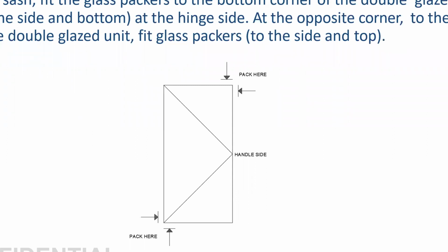The thickness of the packer may be from 2 mm to 10 mm, depending upon the gap between the glass and your outer frame, and the position depends upon how much lifting you need, the profile you have used, and the glass you have used. It depends more on practical experience, on what is practically required. Rather than going theoretically by the charts, one should know the logic of where to fix, and you should carry the packer and some silicone so that the packer doesn't come out.